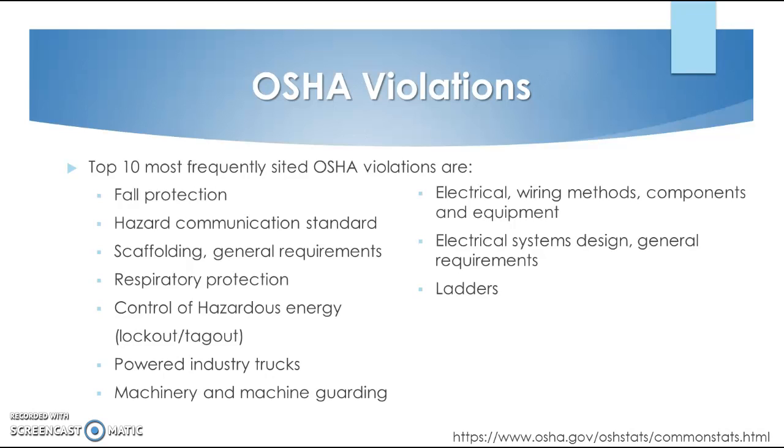The third most common violation relates to scaffolding general requirements in the construction industry. Workers should be making direct connections to floors and roofs and be using counterweights to balance adjustable suspension scaffolds so that the scaffolds are capable of resisting at least 4 times the tipping amount. Not doing so can be life-threatening and is an OSHA violation. In addition, each suspension rope workers use, including connecting hardware that is used on non-adjustable suspension scaffolds, should be capable of supporting, without failure, at least 6 times the maximum intended weight.